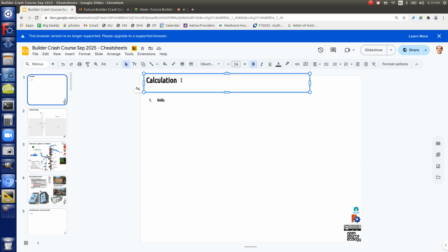Okay, steel, square inch. How much can you hang off a 1 square inch cable? That's determined by the tensile strength. It's determined by its essential property called pounds per square inch tensile strength. And in steel, because it's isotropic, it means it's got properties the same in one direction as another, so compression and tension are typically the same. The hardest steels are up to about 140,000 psi. So if you got that super tensile cable, that's 140,000 pounds per square inch.